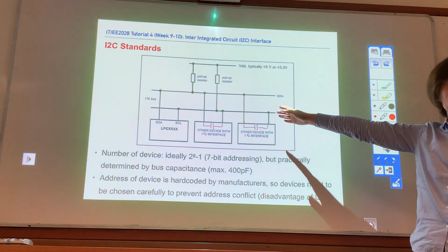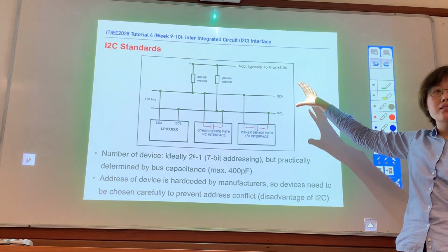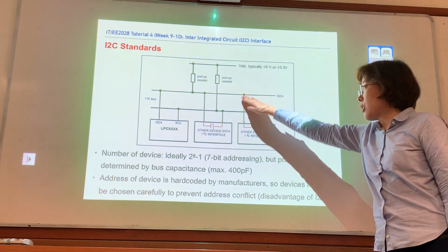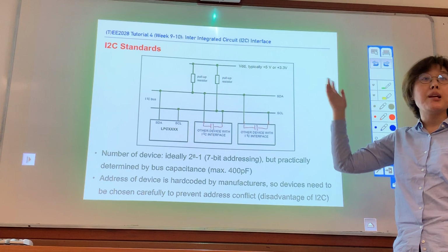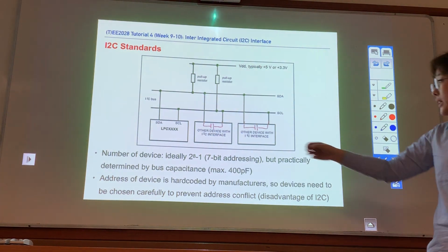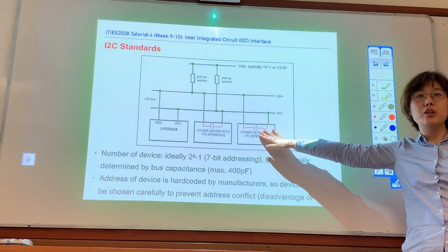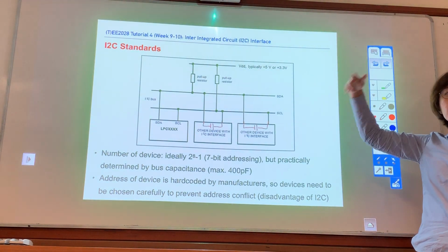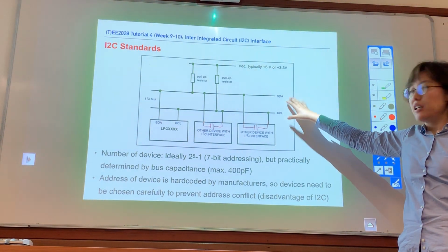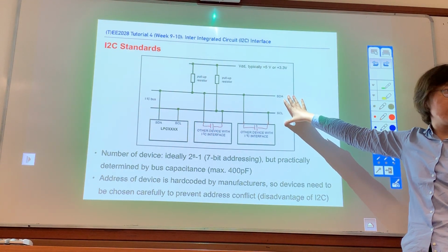That's the final result, meaning it's an open loop, right? When you just turn on the voltage, it starts to charge the capacitor, and your circuit will get stabilized after some time, because the charging takes some time. If your capacitance is very big, it takes longer to charge to full, or if you disconnect, it takes longer to discharge. So with bigger and bigger capacitance, your system becomes stabilized very, very slowly.